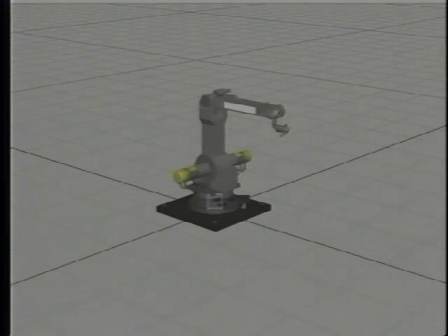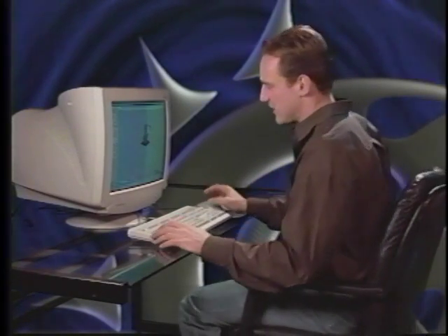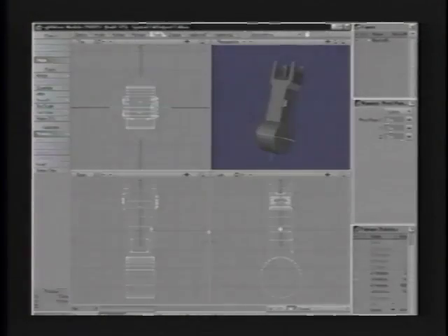Okay, so that's a cool way to update those layered object files. So what you want to do is take your old models that consist of several different object files, load those in, copy each model object file into a second layer or a third layer in one object file itself, and then save that out. Move your pivot points, of course, prior to saving. And then when you bring that one object in, you've automatically got all those layers split out for you and ready to animate.